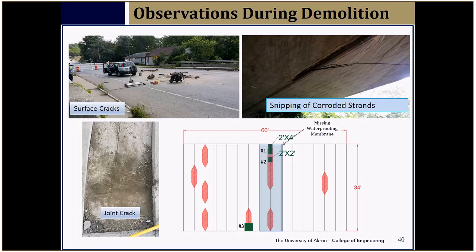But fundamentally, does it change the outcome with an asphalt wearing surface? That was my question. I don't know if it does. A previous research project indicated that those joints are cracked before you get off the job. Right? Temperature differential, which you place the grout versus the temperature of the boxes. Again, you've got a differential there, you get a big heat sink.